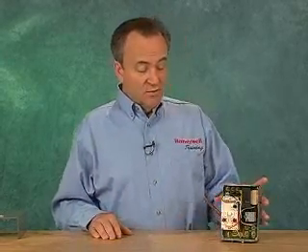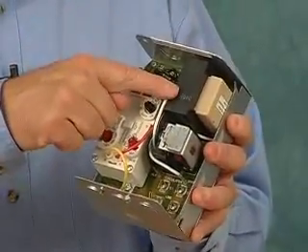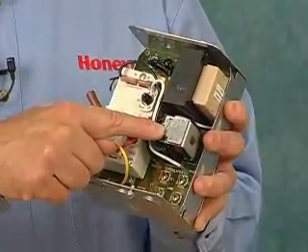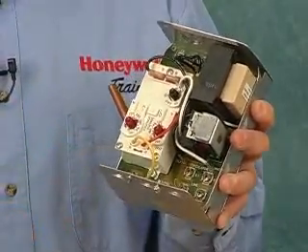It gets used on boilers that not only do space heating, but also provide domestic hot water by the use of a tankless heater. In order to do this, an additional control function must be added, that of low limit. There are different models of the L8124 designed for gas and oil burners with line, low, or millivoltage control. Here's what it looks like. It has a transformer to power the control circuit, a relay to switch the circulator and burner, and all the terminals needed to wire it up.